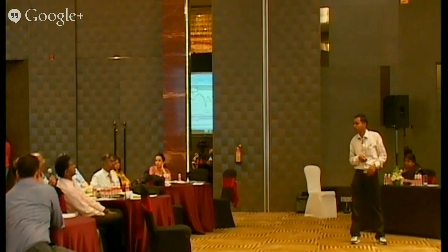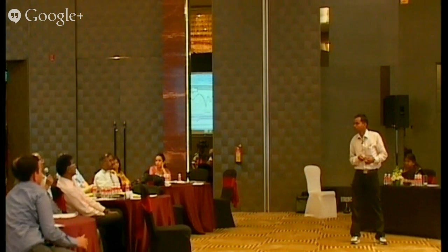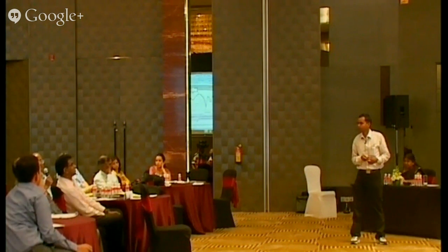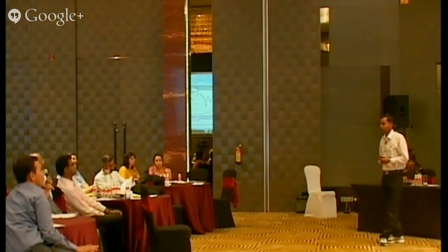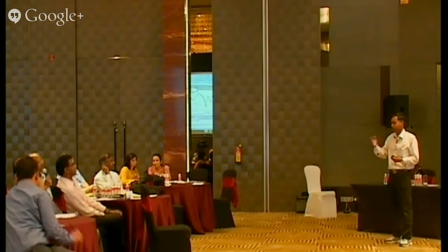In terms of what we call TMmn, like that. Then only you can say that it is this mode. Right now you are saying fundamental mode, dominant mode, and higher order mode. But which higher order mode belongs to which particular mn value? Can you give that? mn equal to variation along x and variation along y, current variation. So TM 0 1 mode, 0 m n.